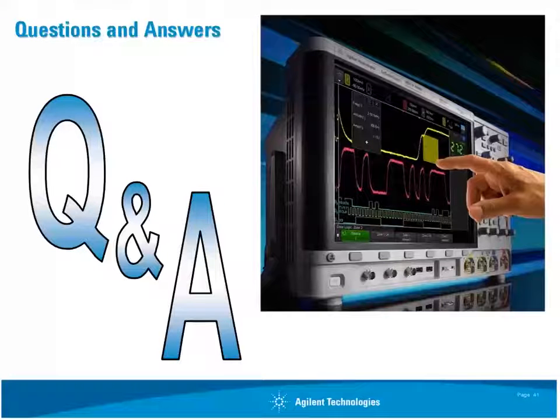The primary purpose of trigger hold-off is to trigger on a burst of signal, so the scope can sync in on, say, the first pulse of a burst and not randomly trigger on the second, third, fourth, 100th, whatever. That's the primary purpose of trigger hold-off.